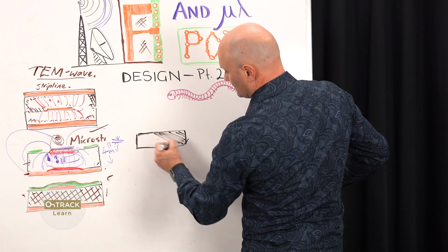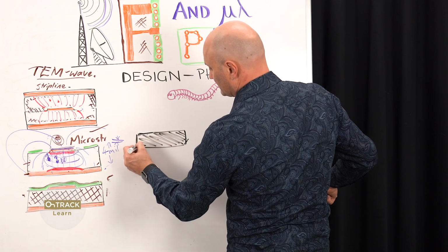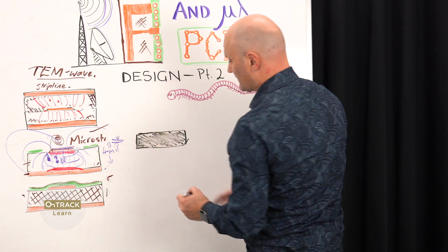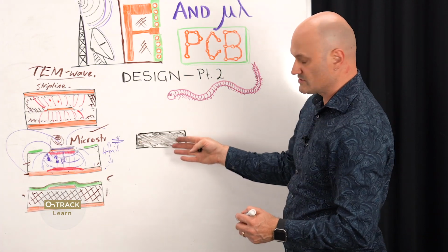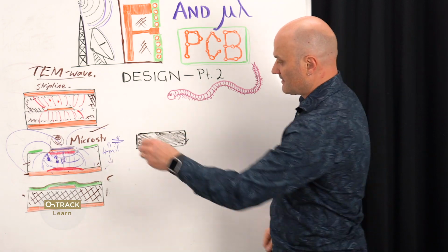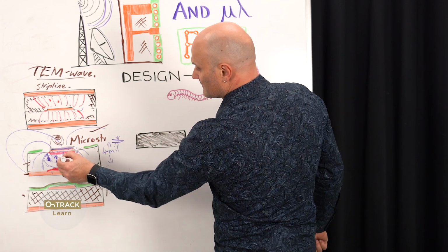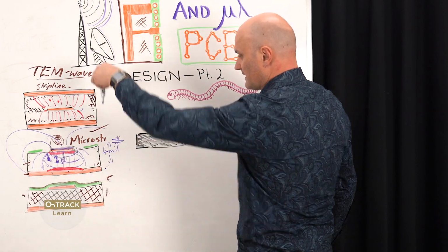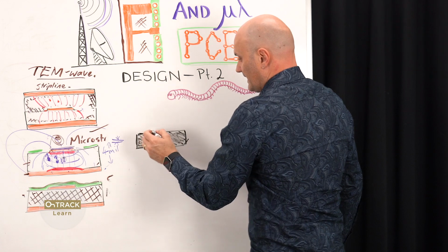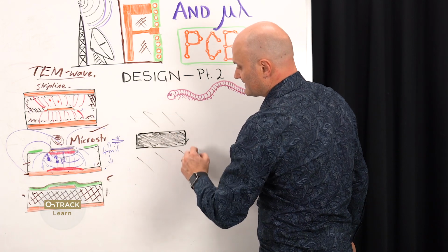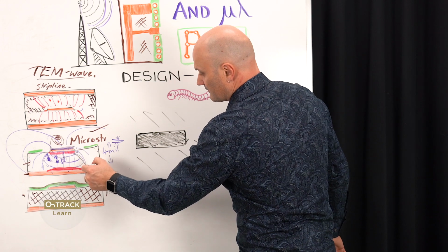And the textbooks will look like this. Now, I've actually seen YouTube videos where people getting into this for the first time didn't realize that that's not just your piece of copper, but there's actually a plane layer underneath it. Like, if we're looking into the structure on the edge of the board here, in this case we're looking down from on top. And so we take for granted that there's a copper plane underneath that as your reference plane.